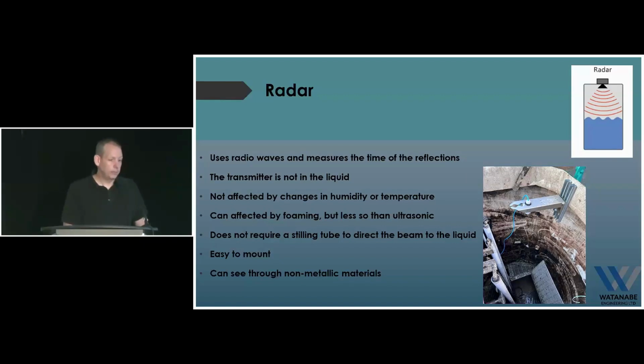So one of the things if you're doing, say, chemical work with these, I know I'm a little bit off topic here, but if you're doing chemicals, you can have a big tank, like a tote, and just mount a transmitter, slide your tote in underneath, and it will look right through the lid. The plastic doesn't affect it, so kind of useful.